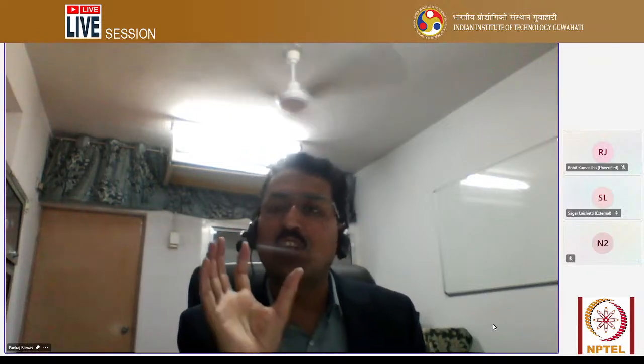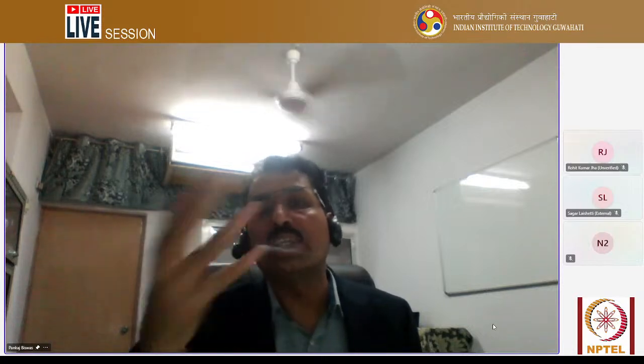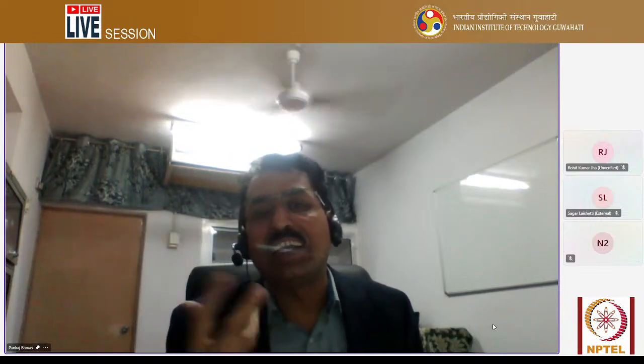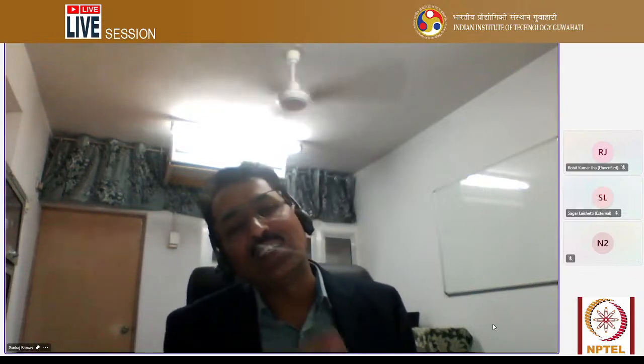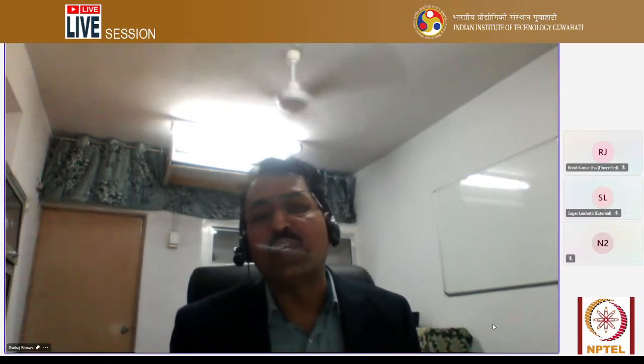Generally CO2 gas is used to generate this laser beam. Apart from CO2 gas, we generally mix some other gases also, like nitrogen and argon, and the major composition of the gas is CO2. So as the light or photon here is generated with the help of gases, that's why it is called gas laser welding technique.